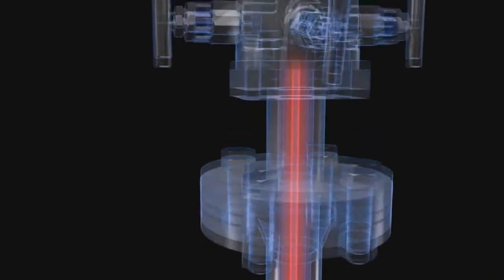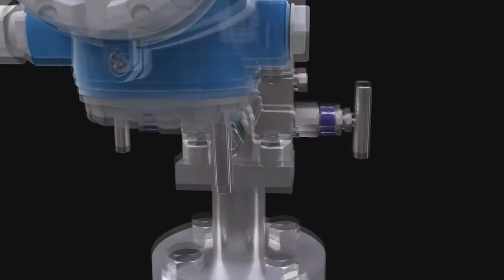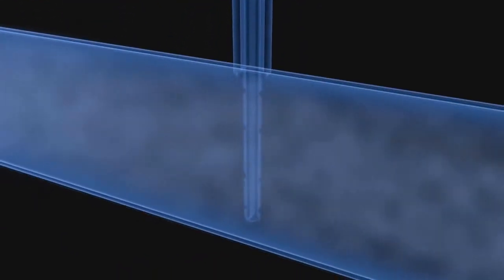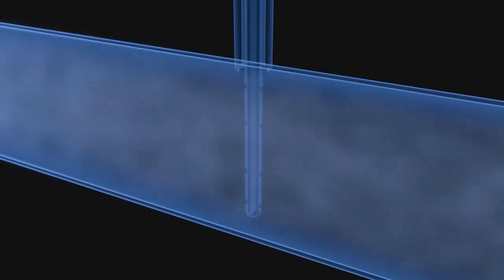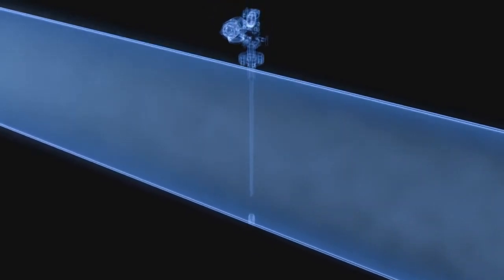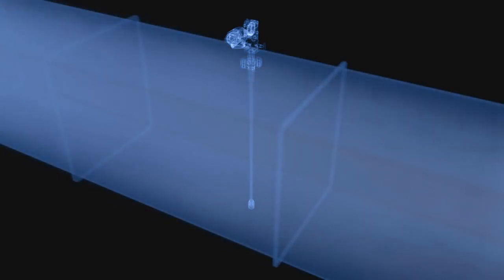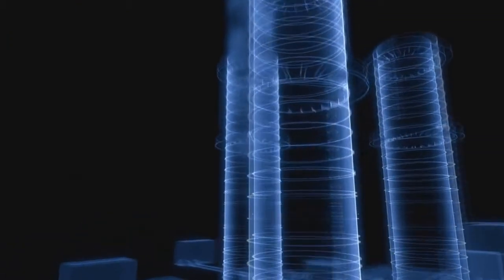Continuous improvements have been made to pitot tubes over the past decades. Devices with a built-in temperature sensor, for example, together with a flow computer, can also calculate temperature-dependent mass and energy flows. This feature is particularly important in industrial processes involving saturated steam or gases. A unique feature is that pitot tubes can register flows in extremely large pipelines. This advantage applies not only to square ventilation ducts, but also to the measurement of flue gas or exhaust emissions in large chimneys of up to 12 meters in diameter.